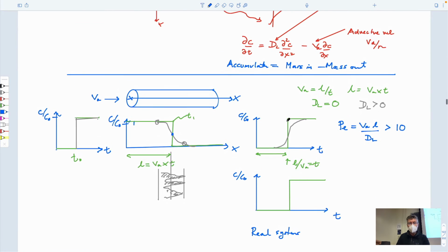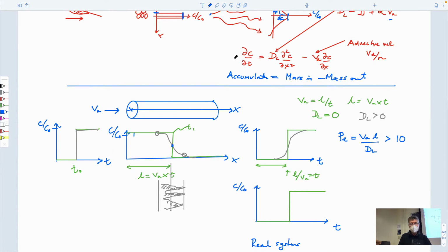And so what we can do is represent this equation as a function of three unique parameters. One is C over C0. One is the Peclet number, which is velocity times length of flow, this might be the length of flow, or it might be this actually, divided by the dispersion coefficient. This is the Peclet number. And I think we call it T sub r, a relative time.